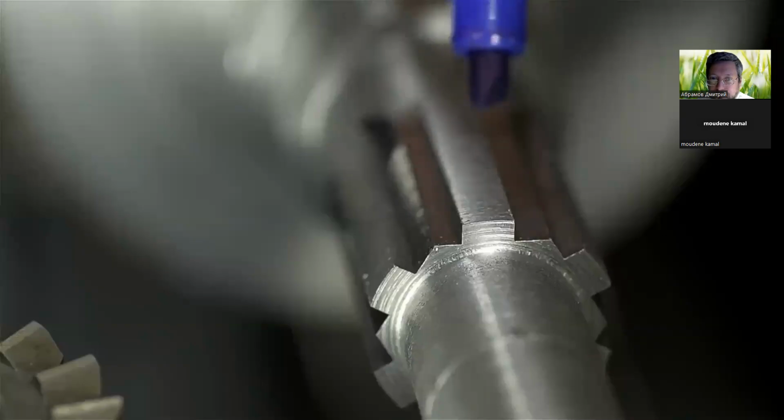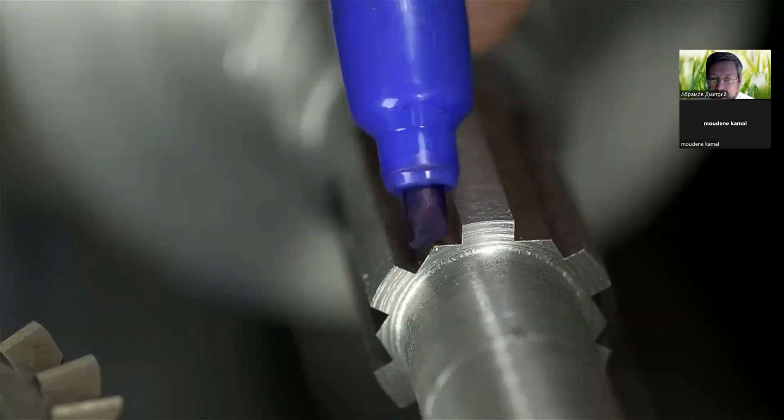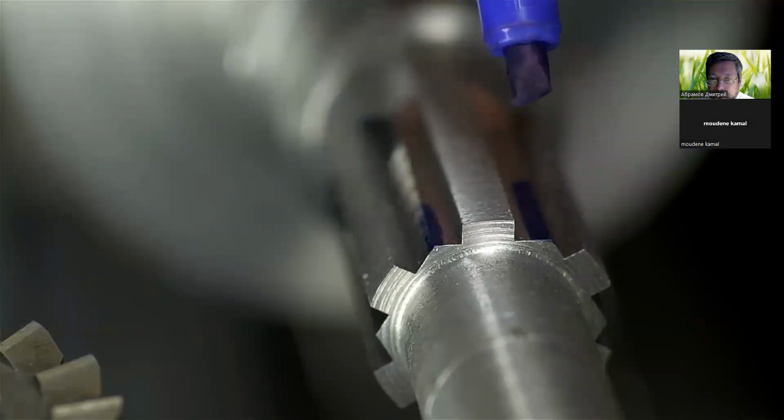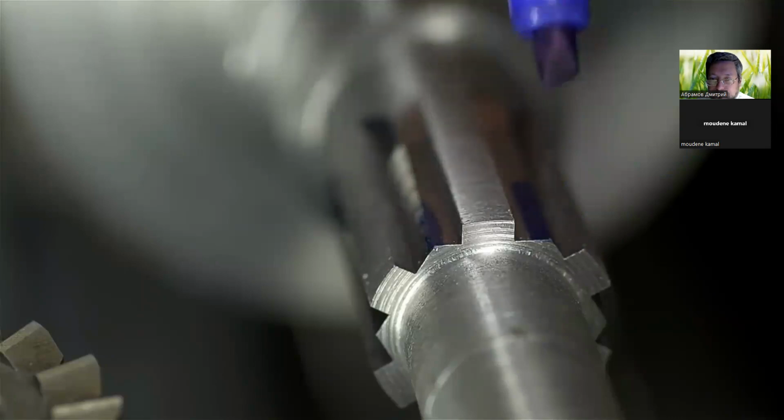And this is what I end up with after 12 passes. I did 6 cuts on one side of the spline and then 6 on the other. It's left me with these little pyramids here. That's the faceting I was talking about earlier. I'm now going to come in, 6 more cuts and try to knock those out. We'll see how that looks and take it from there.